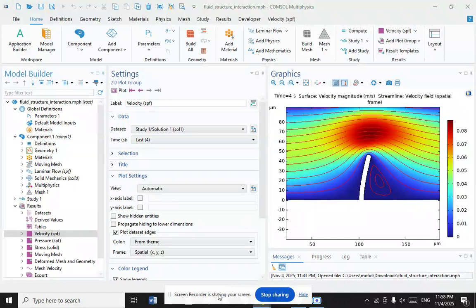The fluid structure interaction problem can hence be written as either a root finding problem or a fixed point problem with the interface's position as unknowns. Interface Newton-Raphson methods solve this root finding problem with Newton-Raphson iteration, for example, with an approximation of the Jacobian from a linear reduced physics model.